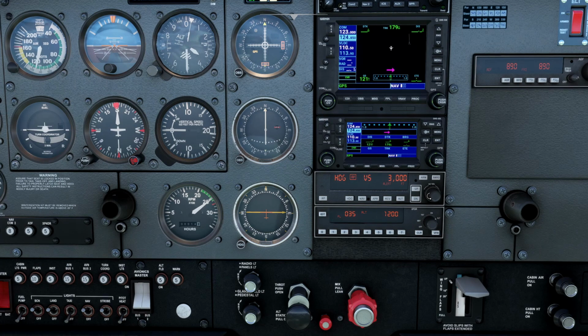An example of that is if I wanted to initiate a descent, let's say to 1,500 feet, so I dial in 1,500 feet in the altitude pre-select display, and then I use the vertical trim buttons and put a descent in there. You'll notice that the display shows the vertical speed momentarily, and then it reverts back to the altitude pre-select display.